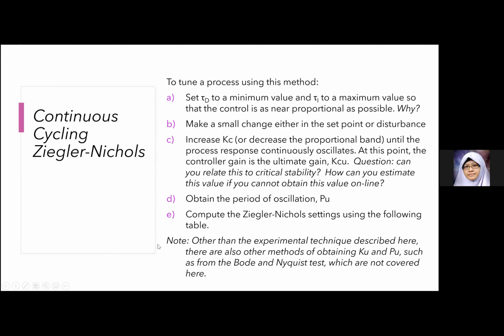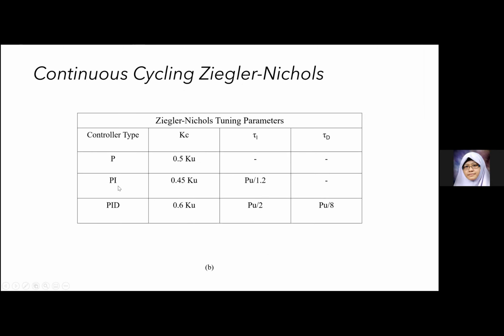Any of you managed to do the Ziegler-Nichols method? Now, Ziegler-Nichols is actually very common. It's a very common method used in industry. So they will increase the gain whenever there's a process shutdown to retune everything. It's quite common in plants to increase it until it's almost cyclical, and then use Ziegler-Nichols, or if it's too vigorous, they will multiply it by a smaller number.